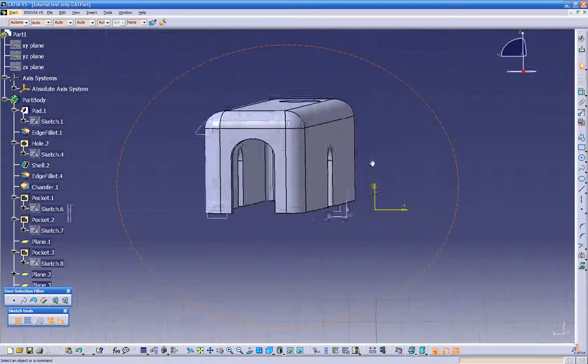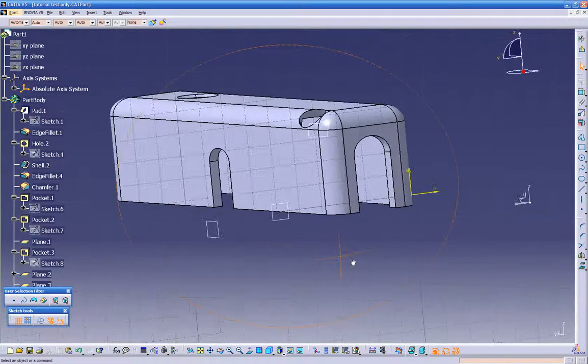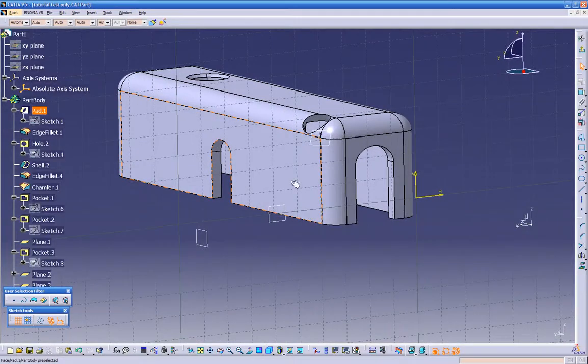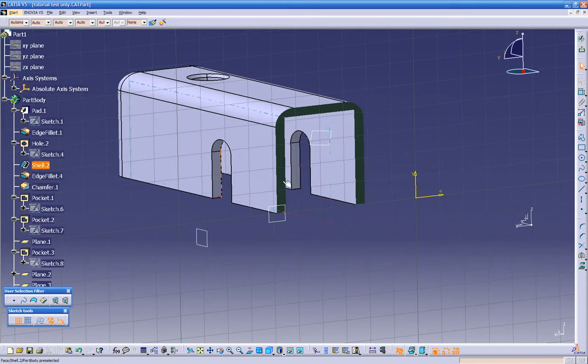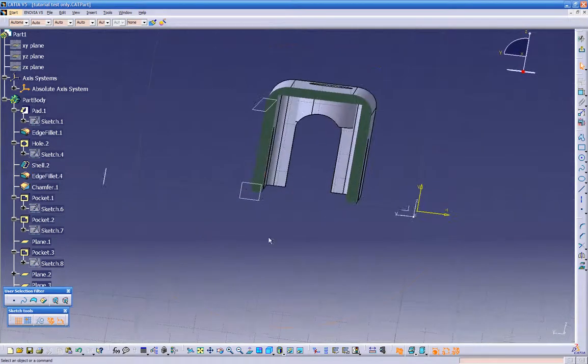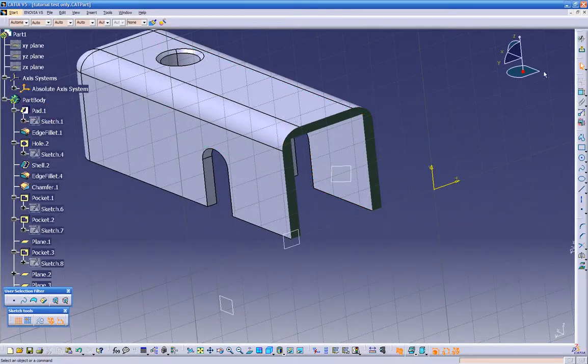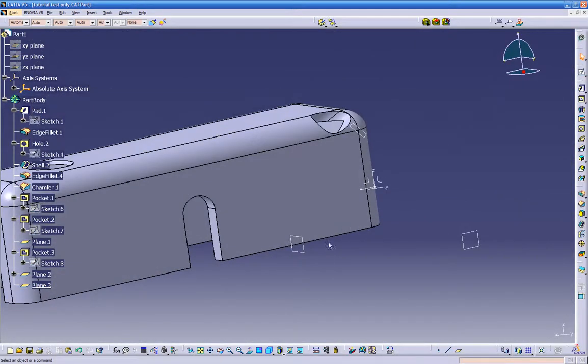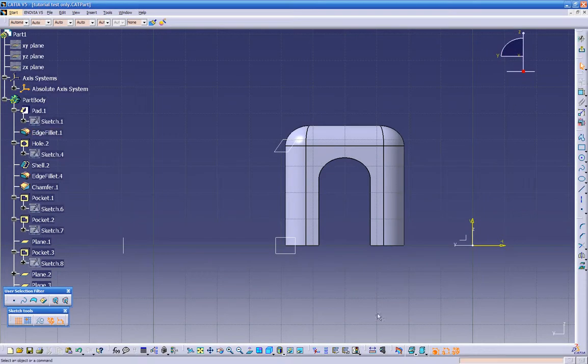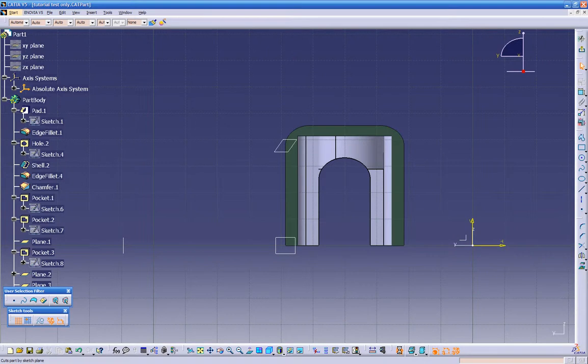Okay, so right now we're working on this sketch right here, but you cannot see what's going on. So what we can do, if you click on this option right here, see what it did? We can see up to that plane, the geometry, but that doesn't mean it's cutting off the geometry. If we get out of the sketch, it's just a construction element. So let's go back on the sketch, and we click on a cut part by sketch plane. So we can see our thickness.